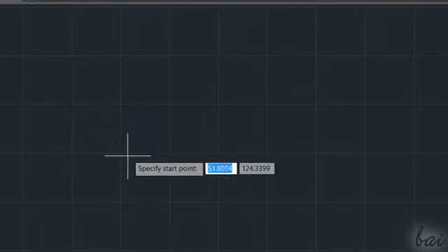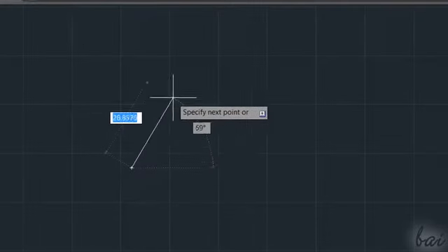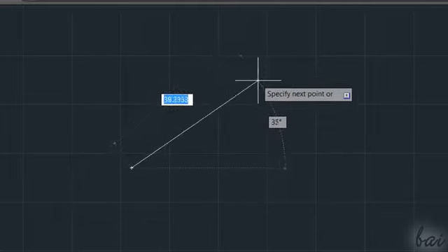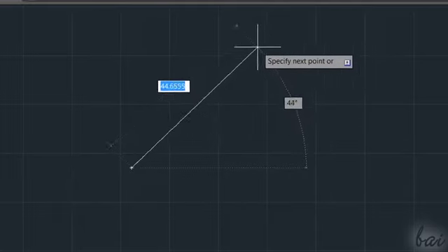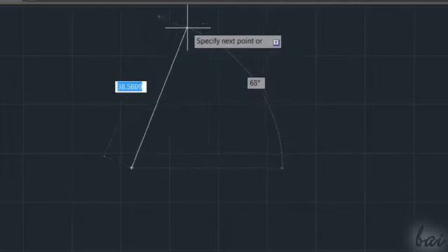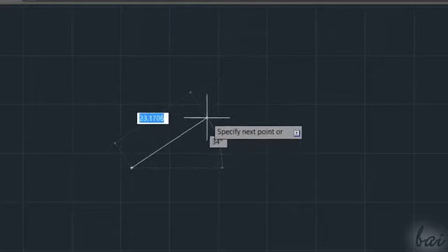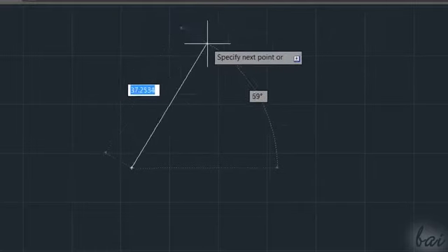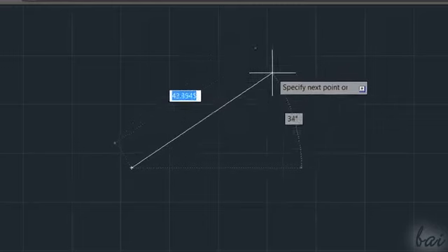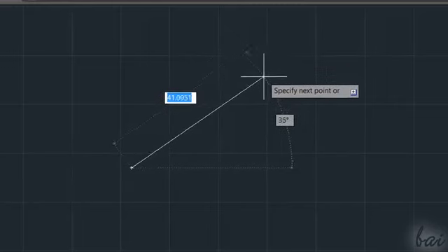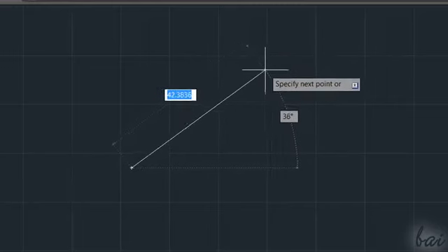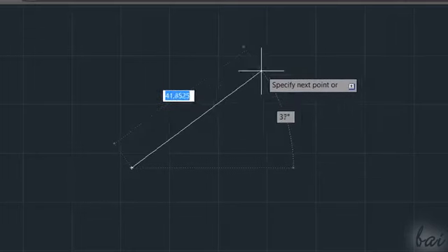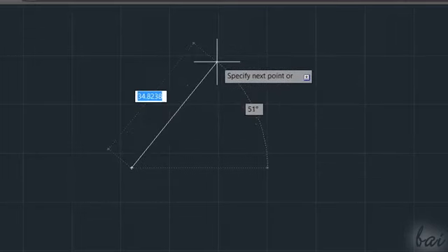While drawing, AutoCAD shows an instant preview of the object in progress and several useful information on it. For example, while drawing a segment, AutoCAD shows its angle with respect to the horizontal direction and the total segment length. By default, angles are measured in decimal degrees and the sides in decimal units.